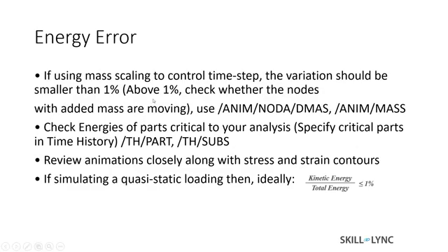For mass scaling, you know that there are huge deformations happening. The deformation of an element might be going out of control, and that is causing all this issue. So to do that, you should always animate the mass scaling, and you should see if there is any unnecessary mass scaling happening in a region where it is not really required too much for analysis.